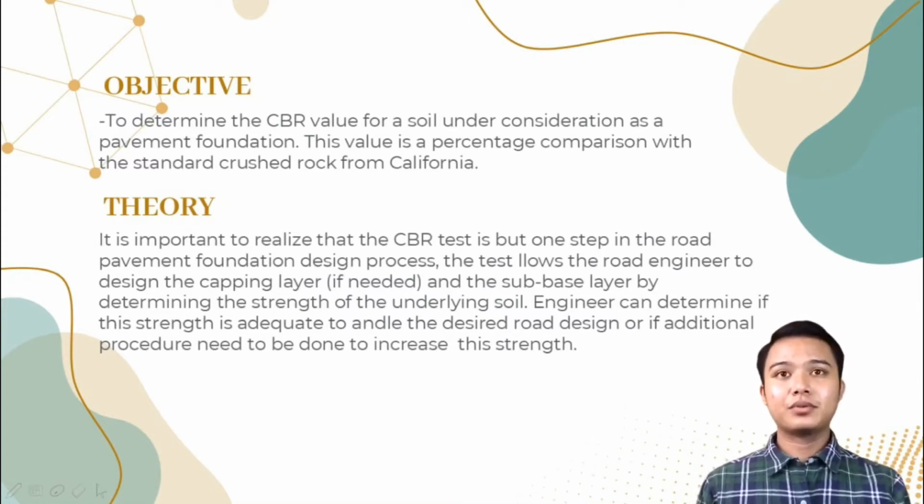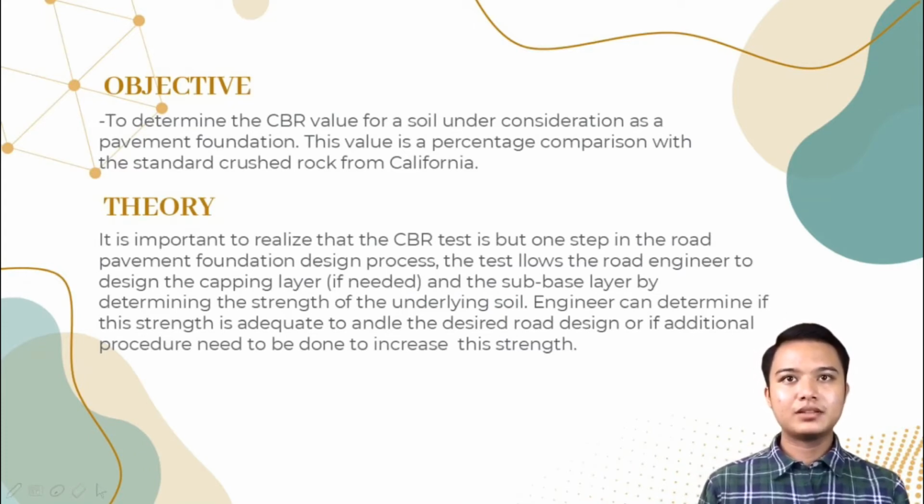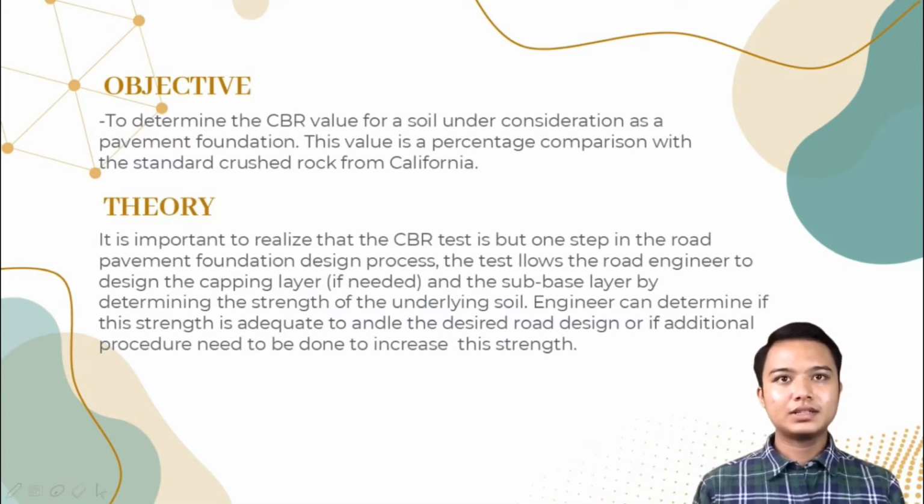Theory: it is important to realize that the CBR test is one step in the road pavement foundation design process. The test allows the road engineer to design the capping layer and the sub-base layer by determining the strength of the underlying soil. Engineers can determine if this strength is adequate for the desired road design, or if additional procedures need to be done to increase this strength.